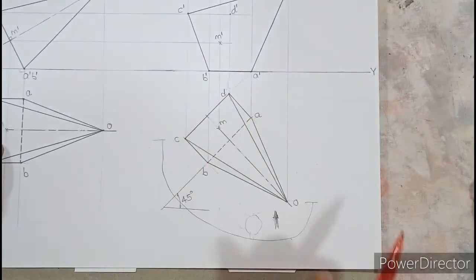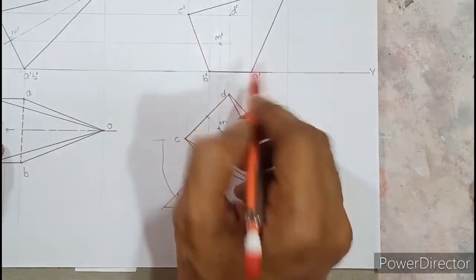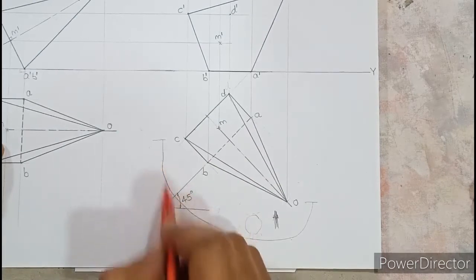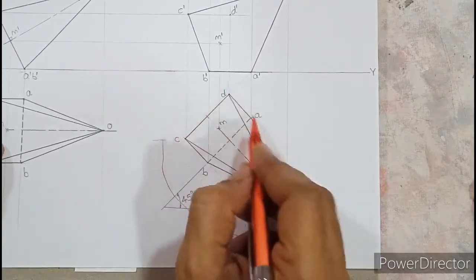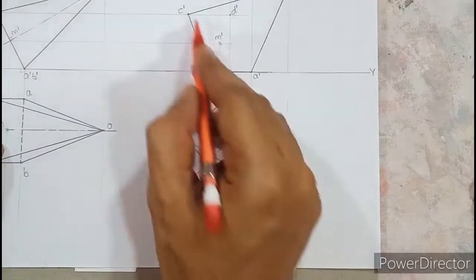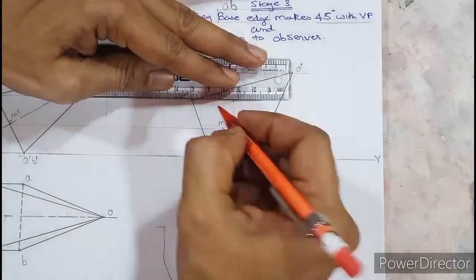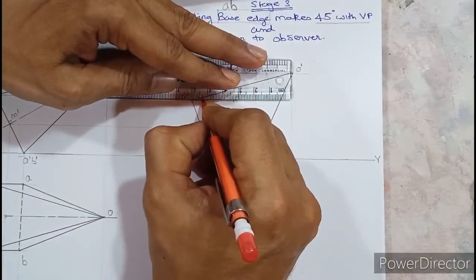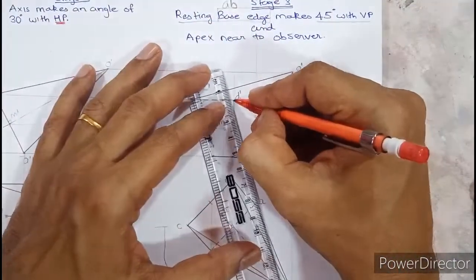So these are the two ways to look at it. Number one, compare O with M. If M is away, draw the base dotted. Second way to look at it is to switch on the bulb from here and emit parallel rays of light. So you can see from O to C everything. You cannot see beyond, so C to D and D to A both will be hidden. Okay, so let us draw a hidden line here. I will connect C to D with a hidden line, and then D to A also.